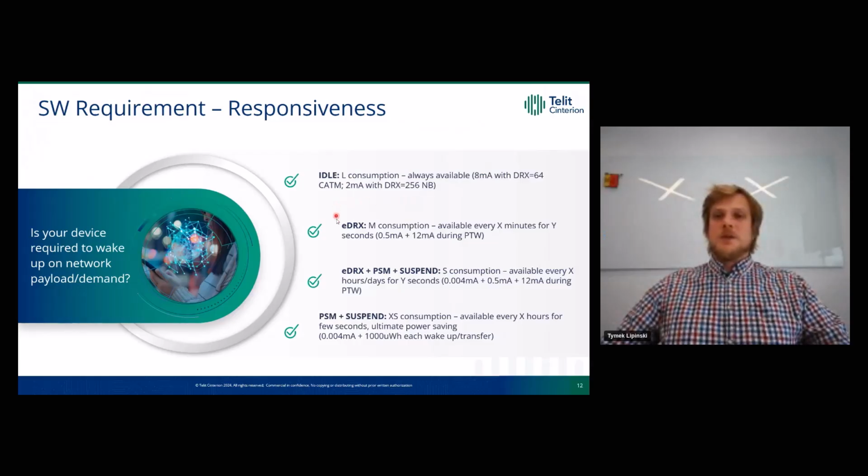Then we have medium consumption of eDRX. That means that the modem will be available every X minutes for Y seconds. So during the X minutes, the modem is consuming 0.5 milliamp, but it's consuming then 12 milliamps during the paging time window, during which the network can probe the modem and wake it up to establish a data connection.